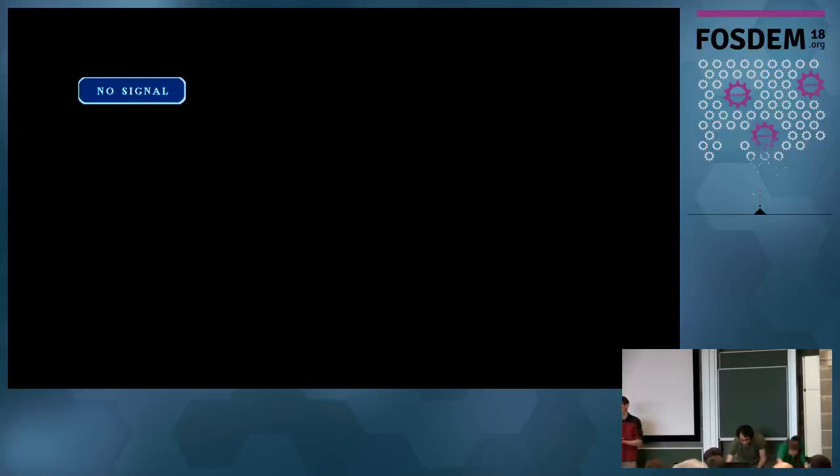So the first reason you might want to do cross-compilation is just that it's so much faster on a big server than it is on a small little device. For the device at the bottom, which is one of these BBC Micro bits, it's a Cortex M0. It's got probably less than 64K on the actual board. There's no way you're going to run a C compiler on that. So cross-compilation is your only option there.